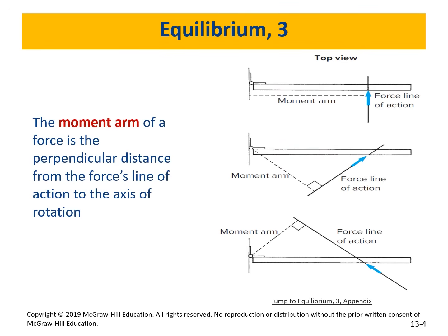Now here's the tricky part. The moment arm of the force is the perpendicular distance from the force line of action to the axis of rotation. So let me show you something. The example that we looked at before, this is the distance, right? And that's the force, and the distance is perpendicular to the line of action. Do you agree? Right? That's how it looked.